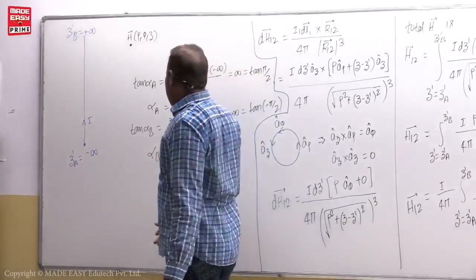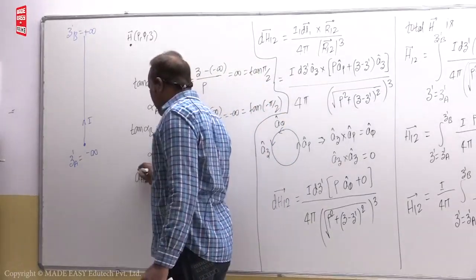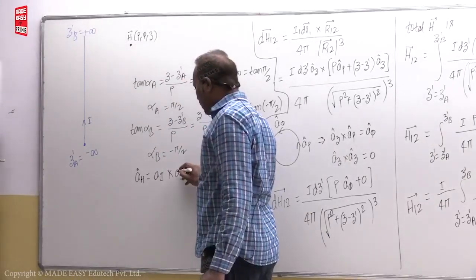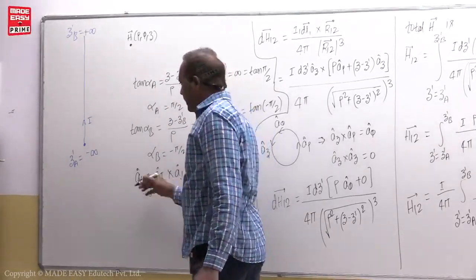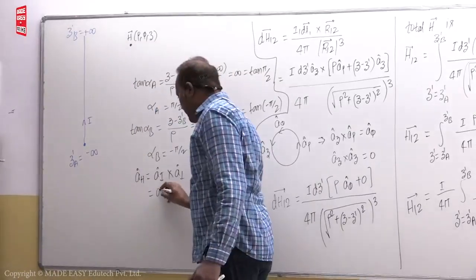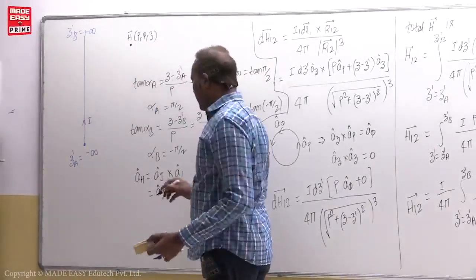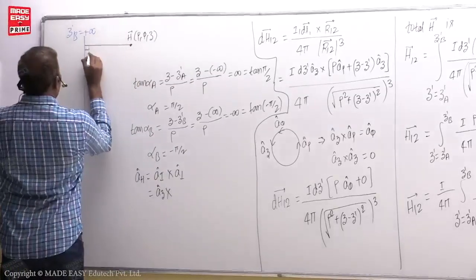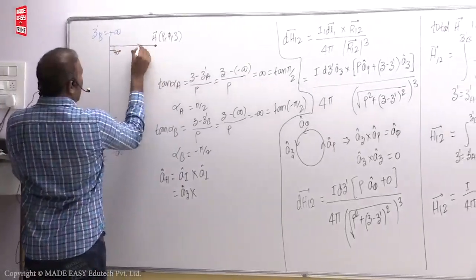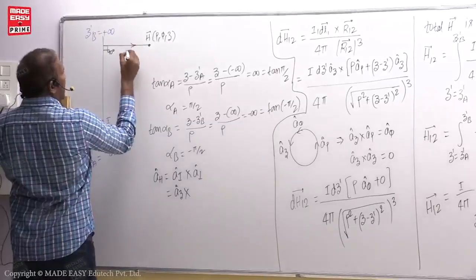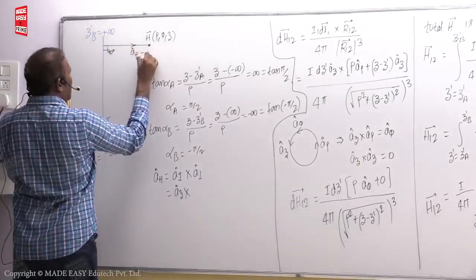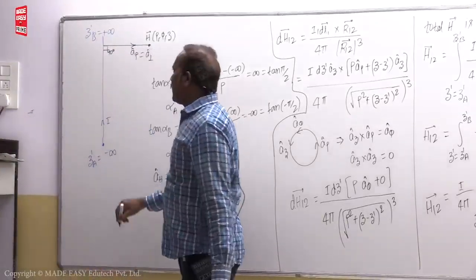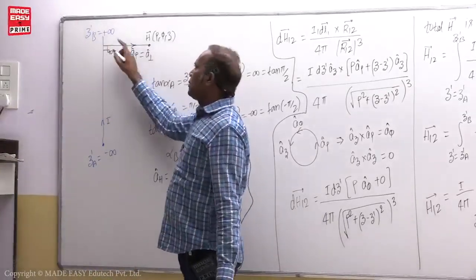Now if you want AH cap, that is equal to AI cross A perpendicular, I told you. Here the current is going directly in the Z direction, so AZ cross A perpendicular. This is actually a 90 degree line. In the cylindrical system, arrow cap is the perpendicular unit vector from the Z axis to this field point.